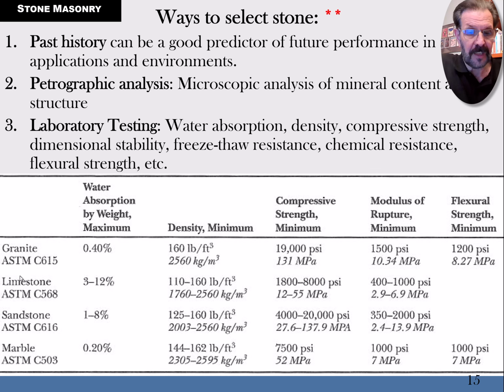Marble can be as heavy as concrete, or some sources can be just as heavy as granite. Whereas you see some of the sources of limestone are much, much lighter. I would suggest that if you got 110 pounds per cubic foot limestone, that's probably the 12% porosity, same thing. So, these are things you can talk about, the compressive strength of the granite or of the limestone or the sandstone. And as you see, the limestone and sandstone, it just depends on the source, because it just depends what it's been through and how much time and compression it's been under.